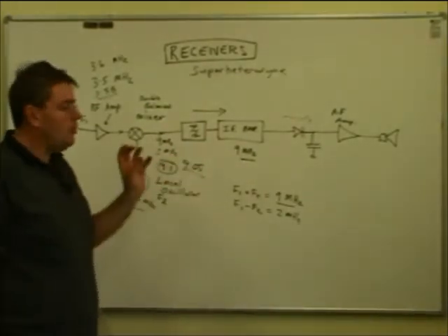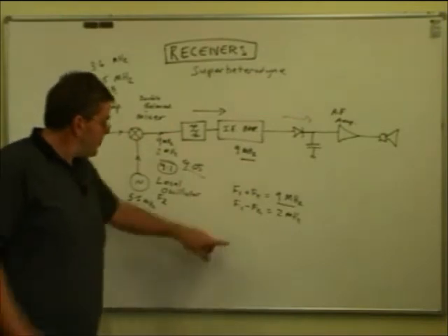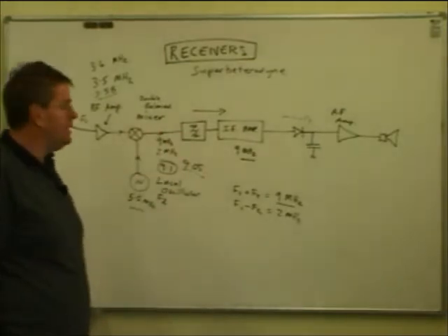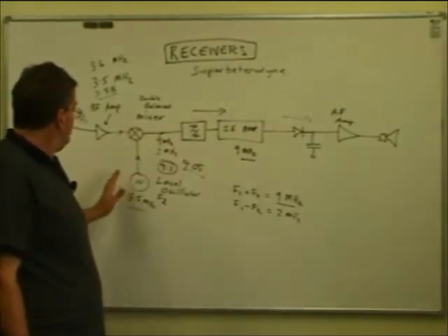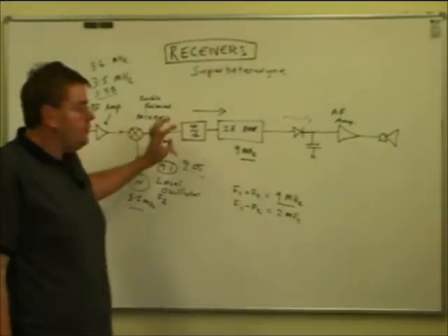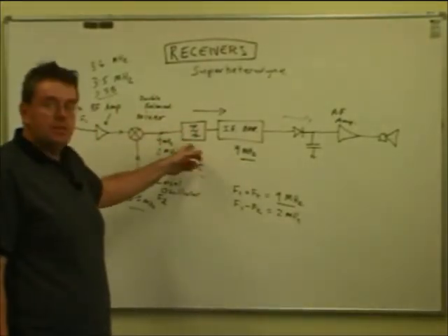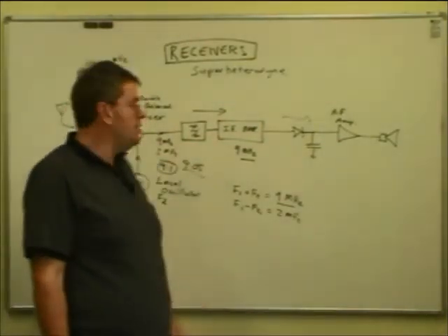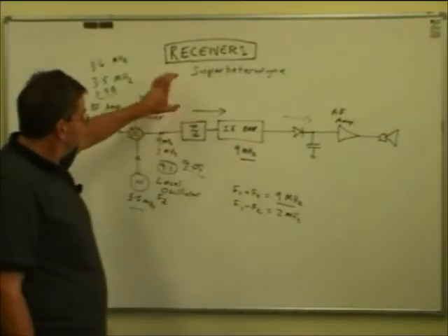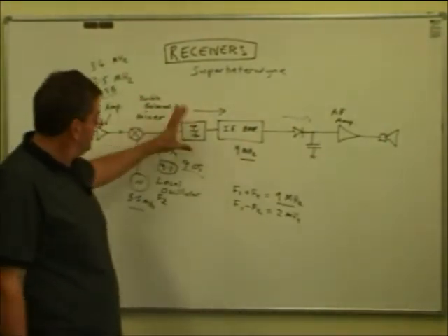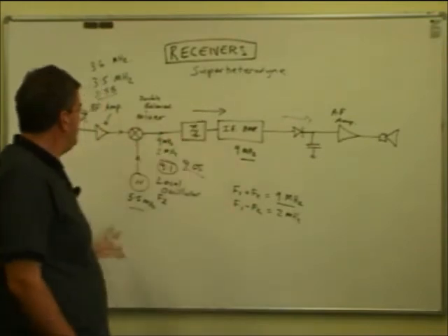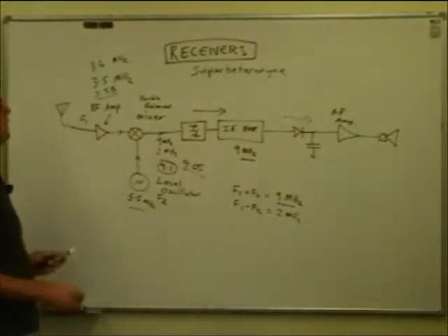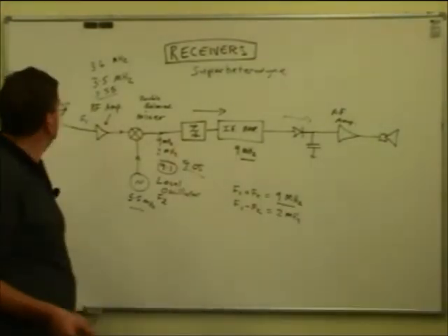So only when you get signals very, very close in, remember I drew that nice rectangular shape of the filter. It's not quite perfect, so signals right next door, you will start to hear them. But you can see the idea that we only have to design and build and buy, which these can be quite expensive, these crystal filters. To get refitted ones for your transceivers, they can be up to 150, 200 US, they're not cheap. So we can just put this expensive device at one frequency and use it for all others by shifting when we want to that frequency. And that's the idea of the superheterodyne. Heterodyning meaning frequency shifting. I'm pretty sure that's what it meant anyway.